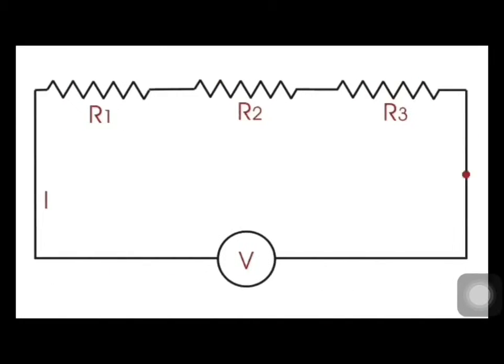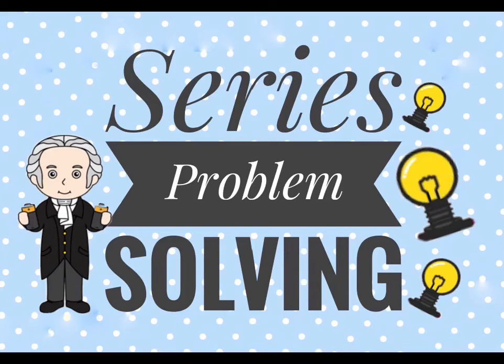The series connection is so named because the resistances are connected end to end and all the charge flowing in the circuit must go through each resistance in sequence. The same current thus exists in each resistance because there are no alternative paths and charge cannot be stored in the wires.